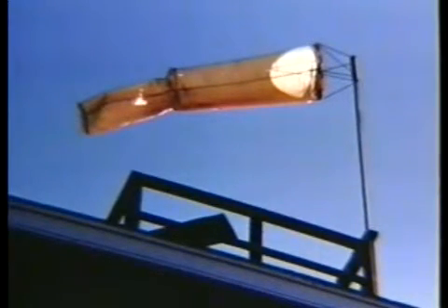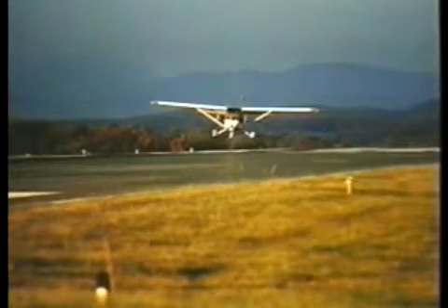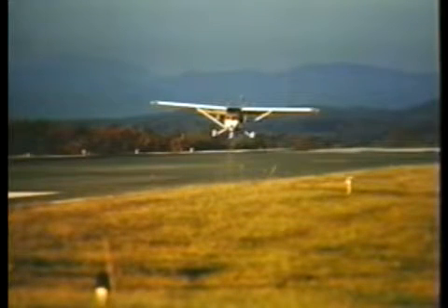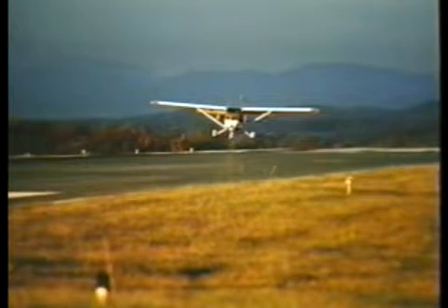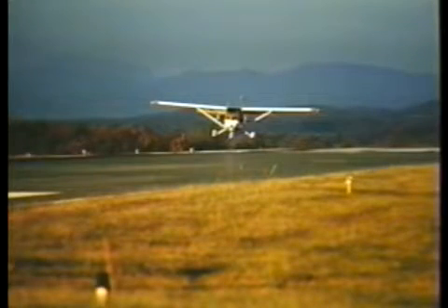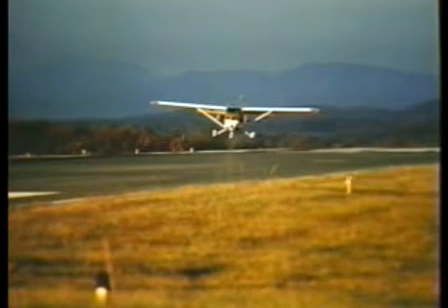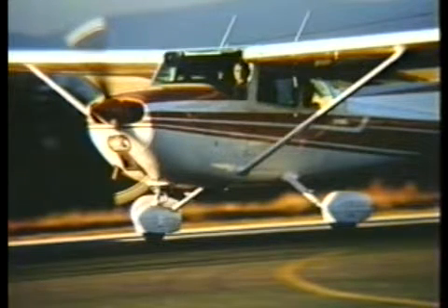We'll address that problem when we talk about winds in a few minutes. And the third is when you're trying to land with an unwanted load of ice. Under such conditions, your stall speed will be much higher, and you've got to carry extra airspeed. However, carrying extra airspeed on short final for any other reason is like carrying a false security blanket, and you're only creating an invitation to land long. And don't think it's going to do any good to force it on at higher than recommended airspeeds either, just so you can say it's on the runway.